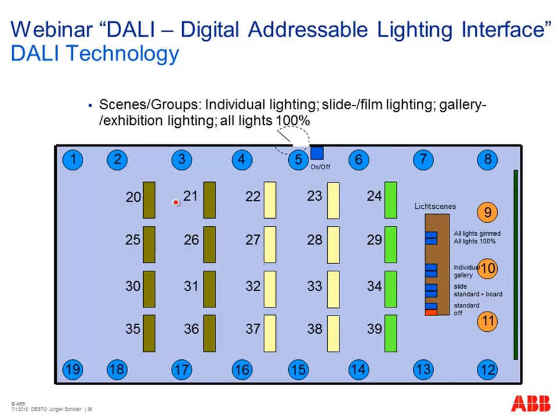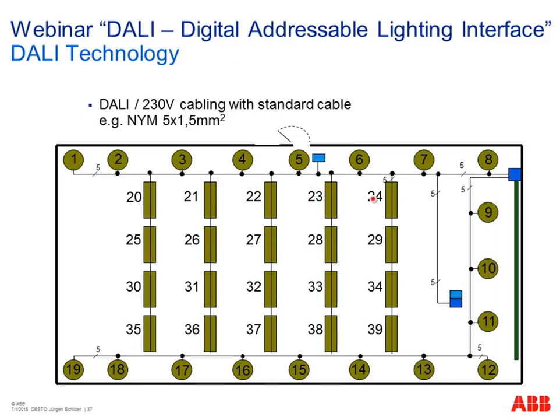So in the traditional way you have to wire to each of our ballasts the cables, but with DALI it looks a little bit different. In DALI we have, for example, here our DB. We need only one cable with 5 cores. Here we go this way, one cable in this direction to connect here all our devices, all these downlights. Here are the light strips, and with a second cable, for example, we connect here these 3 spots in front of our blackboard and the halogen spots like here on the left side of our wall.